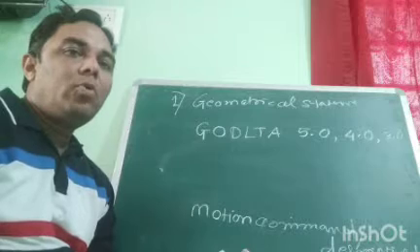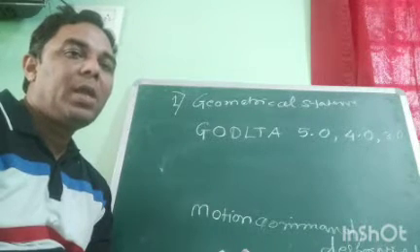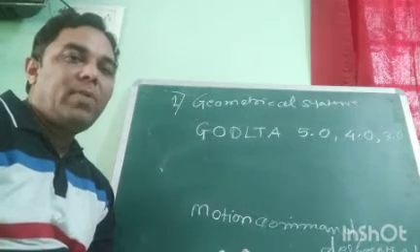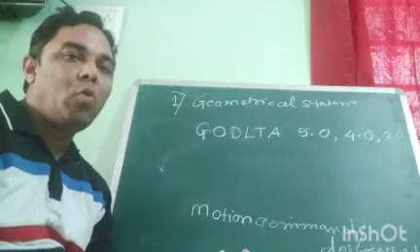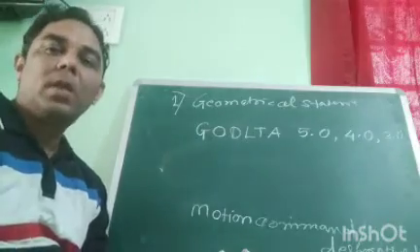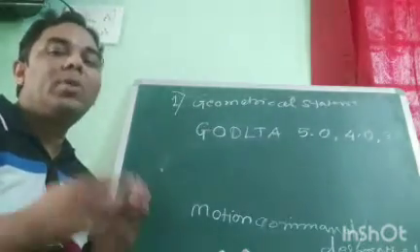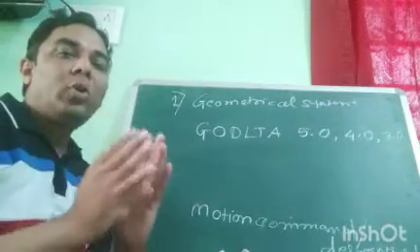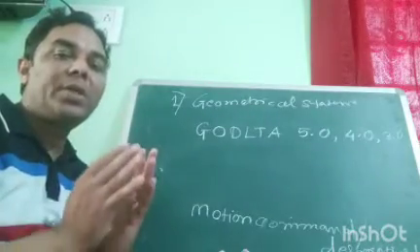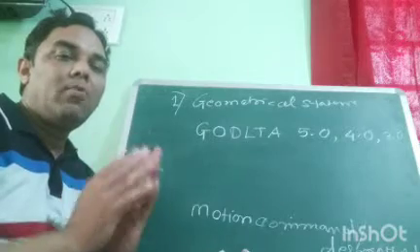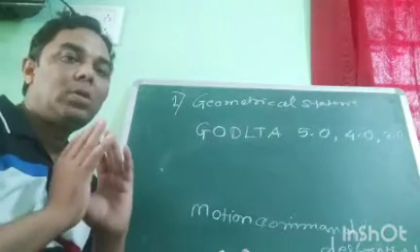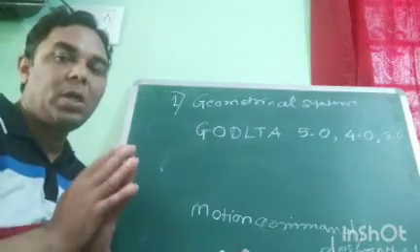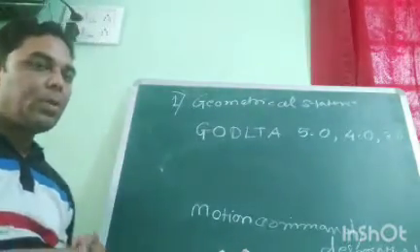The other common motion commands in APT are as follows: from P1, go left, go forward, go back, go up, go down. Basically, with the help of this coding in an APT part program, we are instructing to move the spindle from one location to another in the workpiece, or to move the tool holder or workpiece holder from one location to another in the machine configuration.